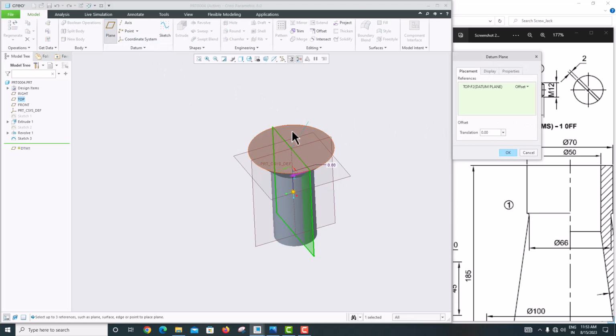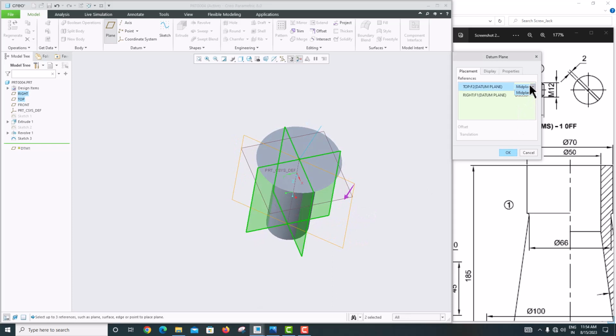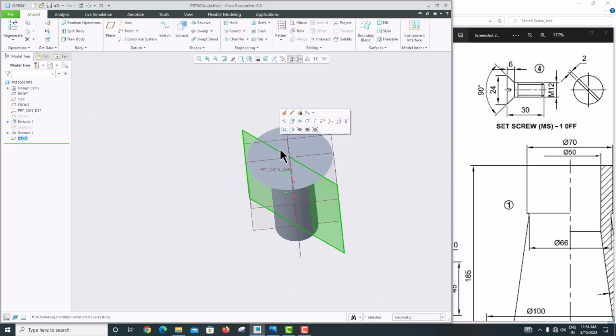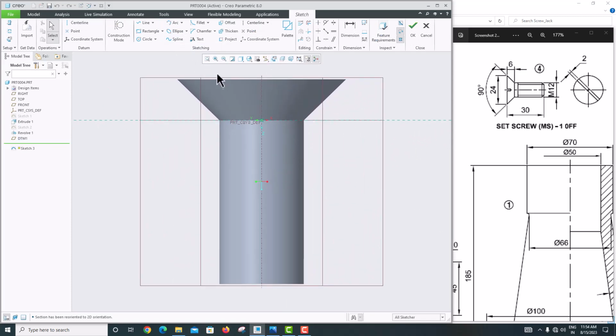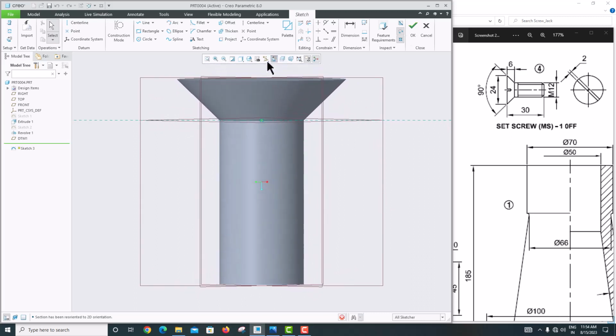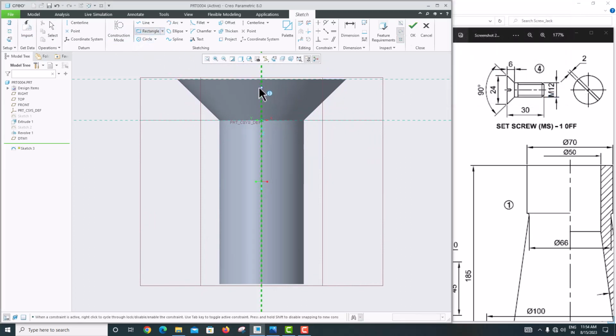Okay. Instead we can go for directly plane. Press the control. Select this plane. See, so automatically it comes mid plane. Say OK. This line is not required. So here we just want to make, take this one, sketch view. Now take a reference, this one, just close. Take a rectangle,